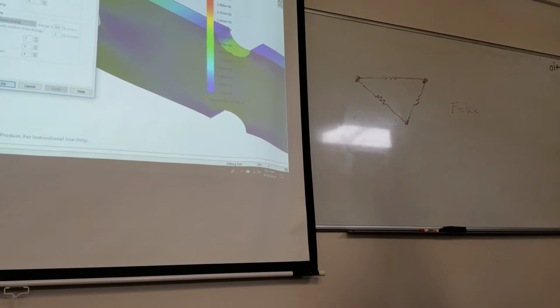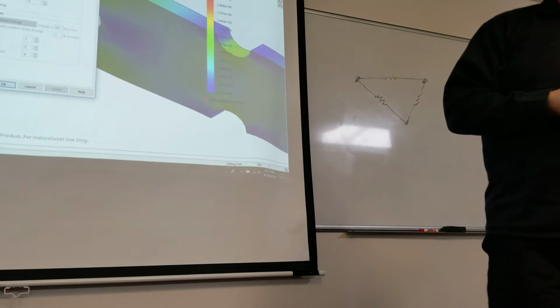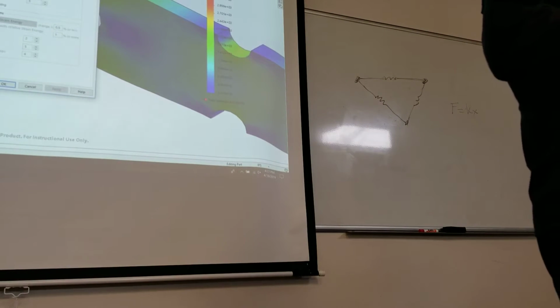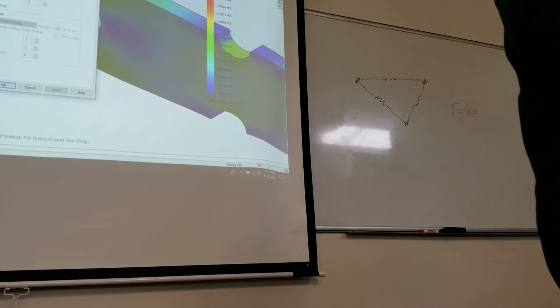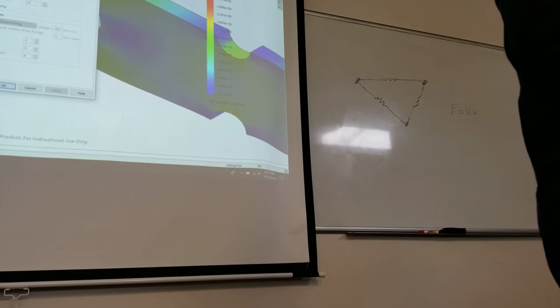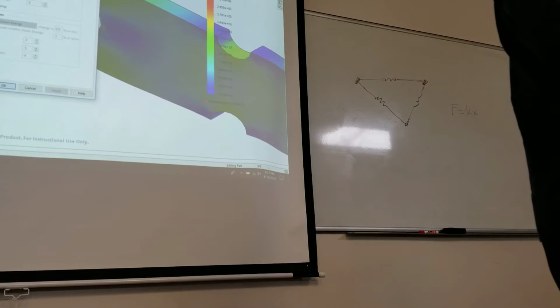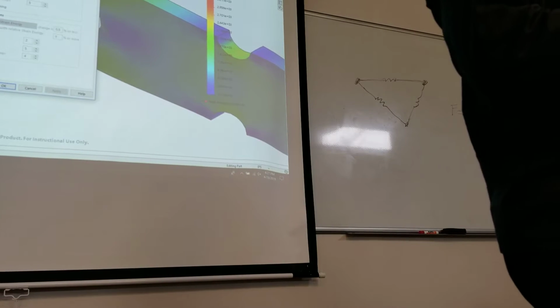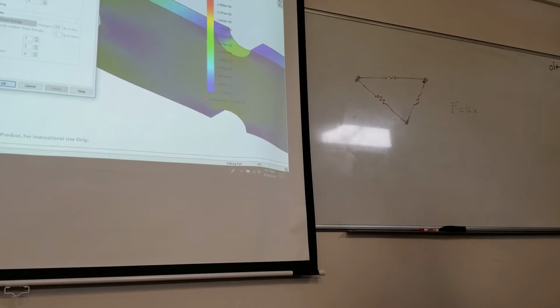Okay? These are what are known as shape functions. They're usually more complex than linear. They're what's known as a shape function, and I can get nasty ones. I can raise the order, so instead of being linear, it can be quadratic, right? Because it's got a squared term, or it can be cubic, or quartic, or quintic, right? And I can raise the order of these, add higher order terms.